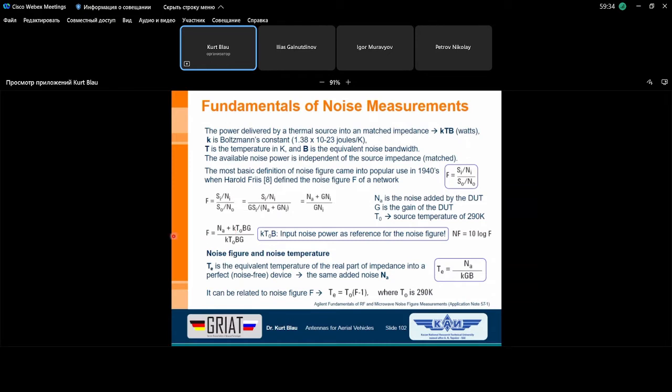So we can determine in every case, whether it's a low pass, or a high pass in connection with a low pass, meaning a band pass, this bandwidth. In one of our last slides, I will show you how we can determine this bandwidth. And I will give you now the keyword for this bandwidth: it's the so-called equivalent noise bandwidth.